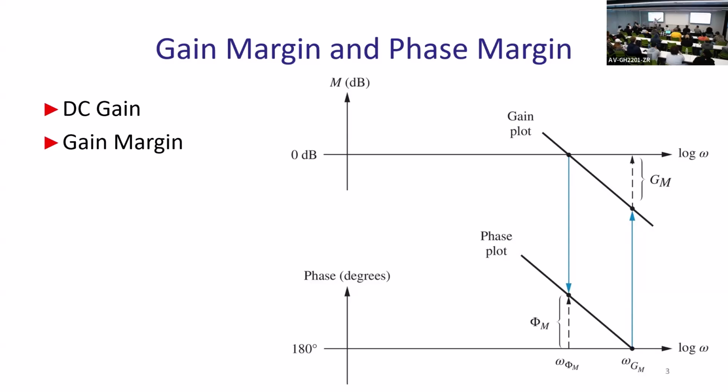This is that part, which means where this function of phase is crossing 180 or minus 180 or 540, negative 540, all the multiples of 360 starting from 180, plus minus. So all of these lines, you will have crossing of these lines, how much gain below 0 dB you have. This is gain margin.